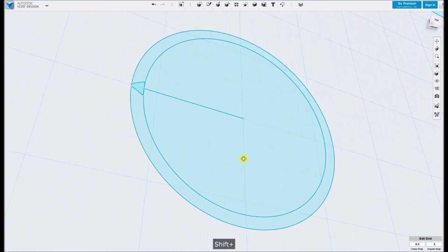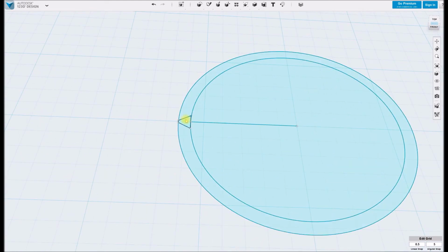The next thing we need to do is reorient it. So click on that, go to move, and since you can see this is kind of wonky, it's on a bit of an angle, so we're going to change the pivot point. So click on start reorient, bring it right over here, click, stop reorient. So now you can see it's actually in the planes that we want to be using.